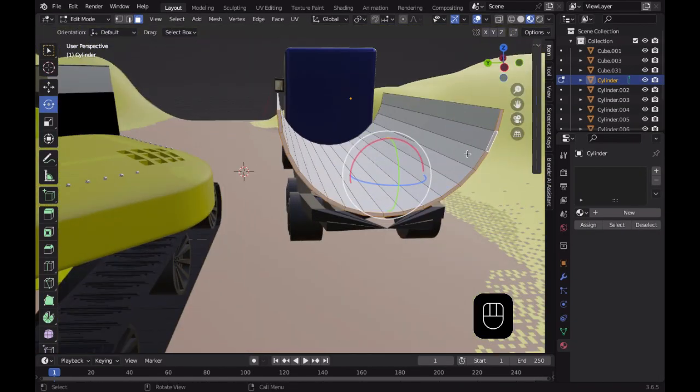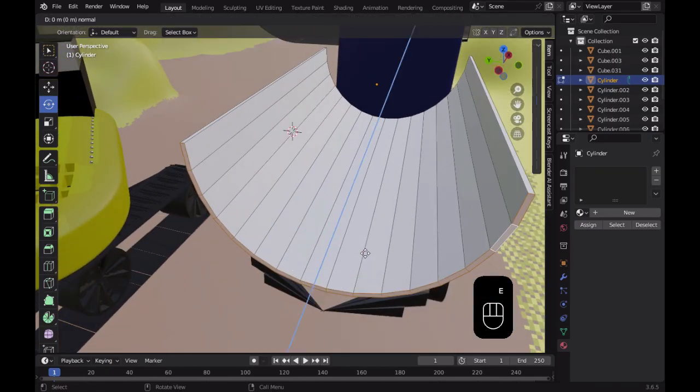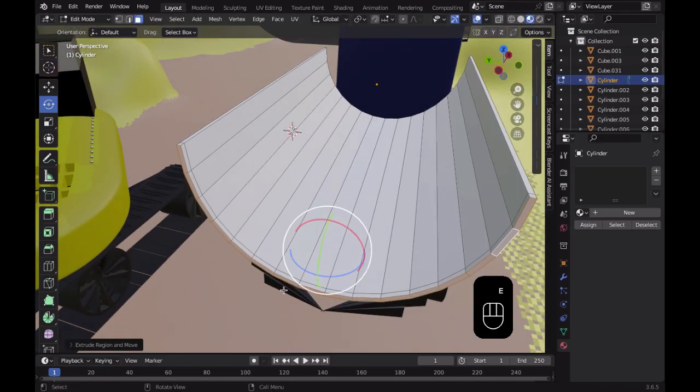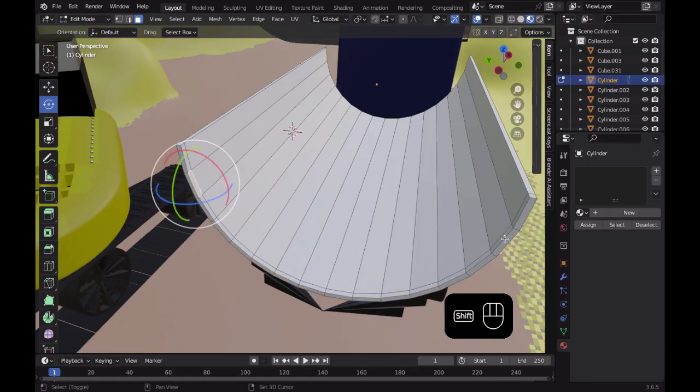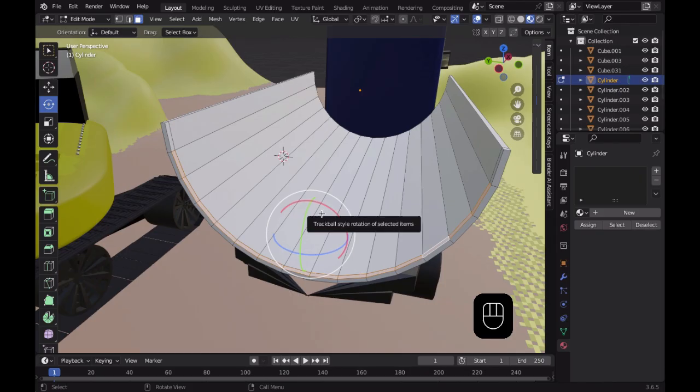So just try and select this one face here, just this line, and then extrude it a bit. And basically what that does, then you can select these inner faces. Okay, wait. Just like this. Wait a second. One second. Done. Yeah, I just skipped that because I don't want to make you guys wait forever.